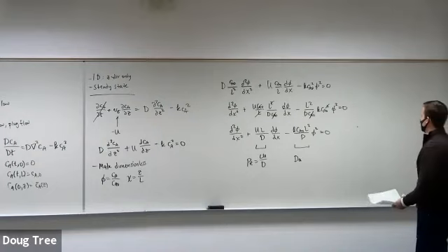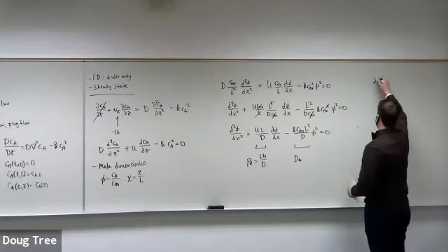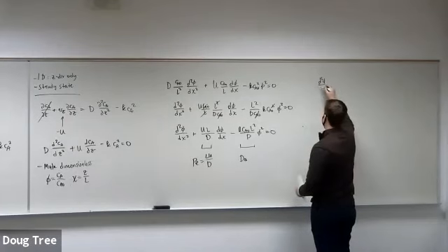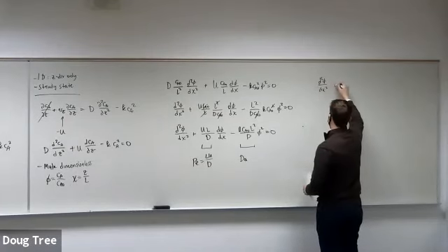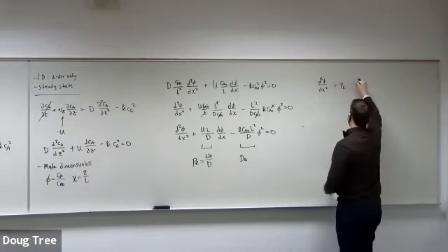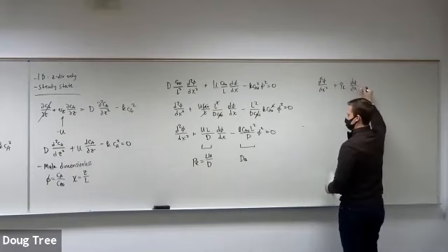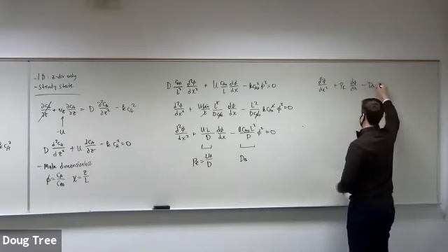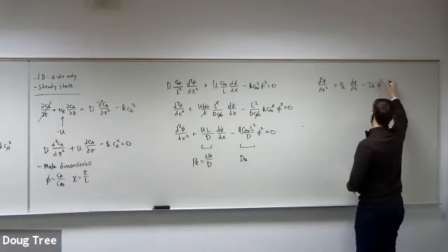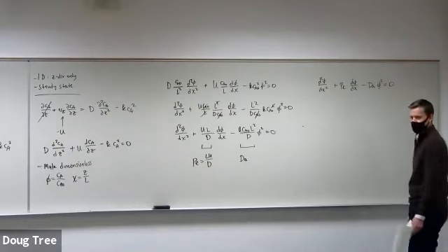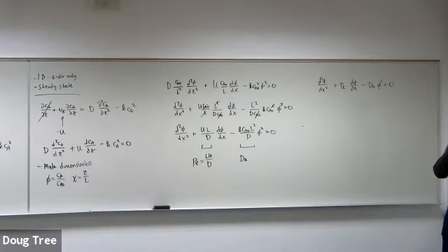All right, so we can write that down now. So we'll put d2 phi over dx squared plus Peclet number d phi over dx minus the Damköhler number phi squared equals 0. Sweet, we're down to two parameters. Two dimensionless groups. And we're going to do one more rearrangement here.